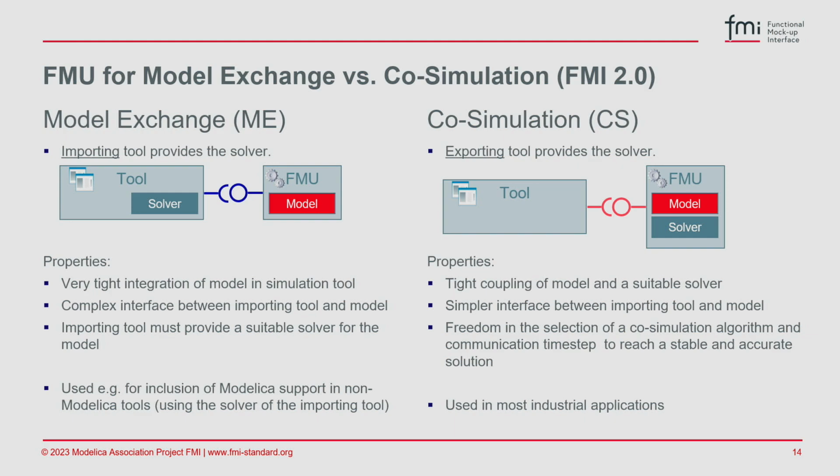On the other hand, there are important use cases for this model exchange FMU. So, for example, if you want tight integration of a model with the solver of an importing tool, then this is the way to go. So, for example, we are here at the Modelica conference. There are some tools who do not have a native Modelica compiler, but who have licensed a Modelica compiler, and they, under the hood, create an FMU and import this and expose in this way the Modelica processed equations to their solver. That's an important use case for model exchange.